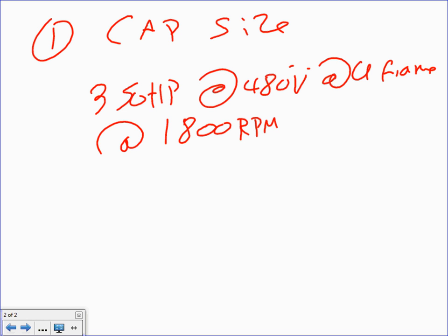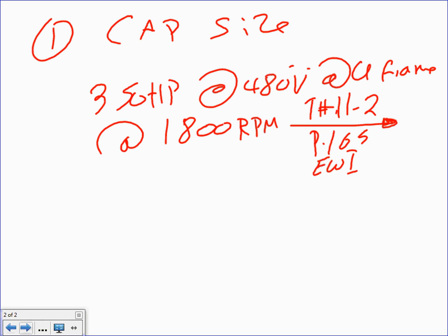Knowing all this stuff, guys, take this one to table number 12-2, page 165, Electrical Wiring Industrial. I know, DJ, you like my errors here. So this is where we're going to take all this information based on this table. 11, not 12. Okay, thank you. 11-2. Based on 11-2, yep, page 11-2. The upper one, because it's U-frame, guys, what's the size that I need? Everybody can see the size? What's the size? 60. My size is going to be 60.